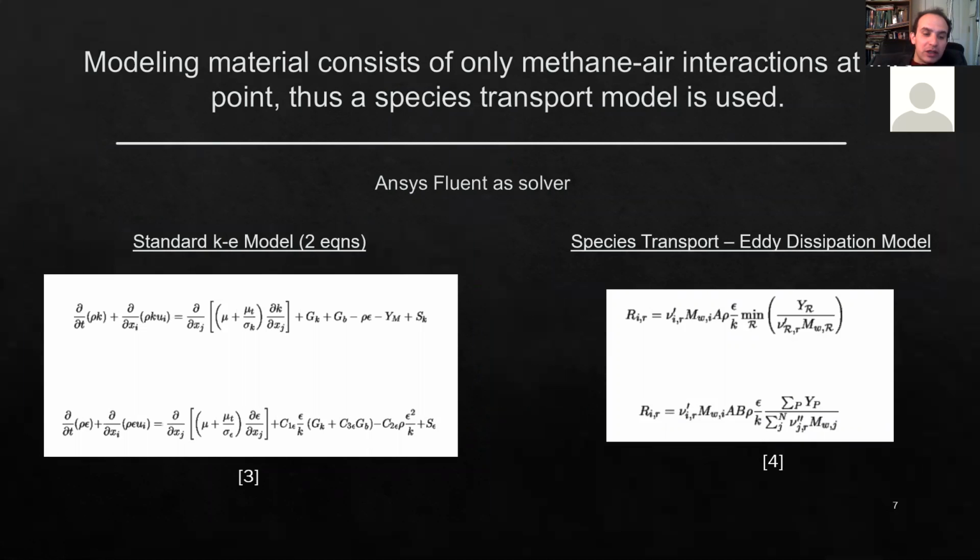So it means that it's not direct numerical simulations because some models are incorporated, so you don't resolve everything. But it's not filtering here, so it runs. It's Reynolds-averaged Navier-Stokes equations, but I believe unsteady runs, as long as you talk about transient phenomena, right? So it should be unsteady runs with the k-epsilon model.